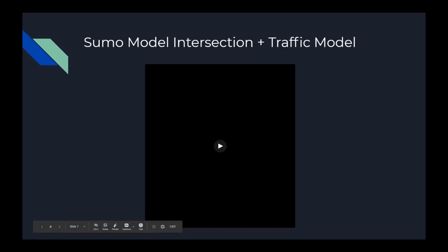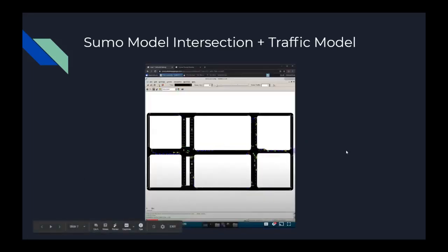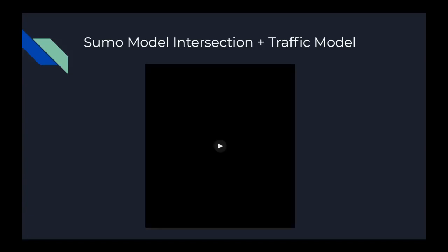This is a video of our Sumo traffic model. Here we can see the traffic lights on both intersections are operational. Notice how the cars attempting a left turn creep up into the intersection, mimicking drivers in real life. You can also see that there's more traffic along the vertical roads. This is because Broadway and Amsterdam are major avenues, while 120th Street is only a minor cross street. Currently we are only using passenger cars, but could explore different models with other vehicles in the future.